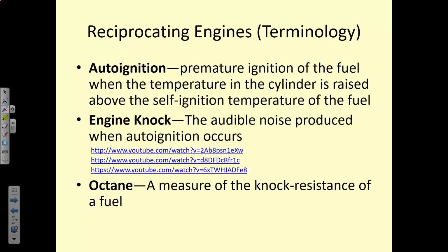And then octane in fuel is what helps the engines to prevent auto ignition and knock. So the higher octane fuels will have a higher auto ignition temperature, so that knock doesn't happen. So in performance vehicles that have high compression ratios, higher octane fuel is necessary.